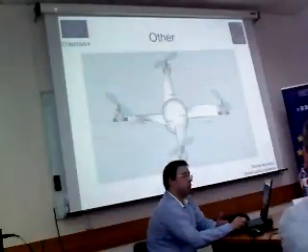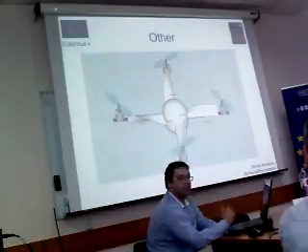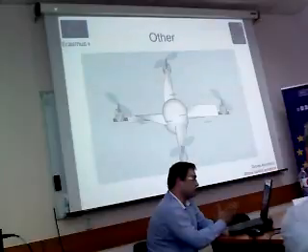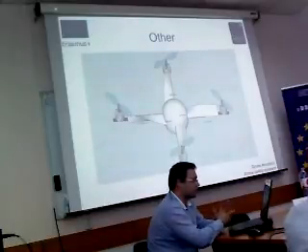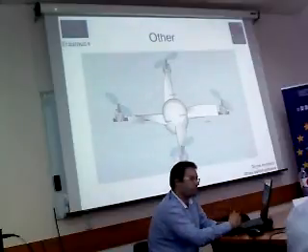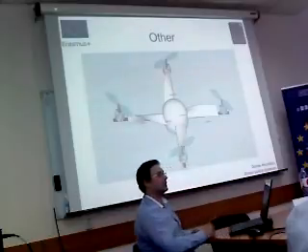And at the end, I'd like to present to you a new idea to increase the safety of UAVs. It is also a solution from last year. The company Teomatics received a patent in the US for an innovative alternative to known safety systems such as the parachute system. This is done by the construction of at least 2 passive lift elements arranged radially symmetrically about the yaw axis of the drone.